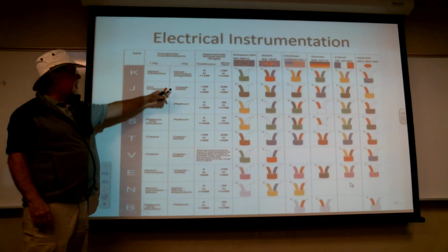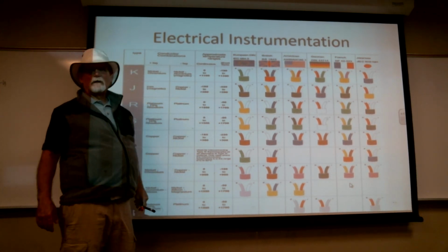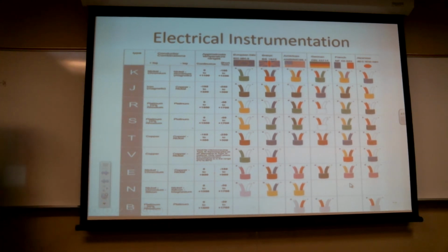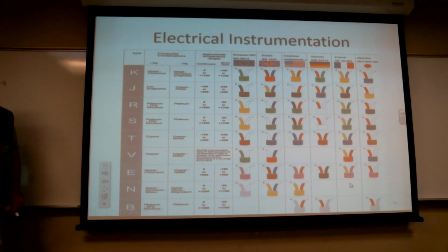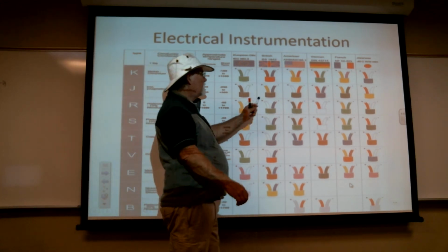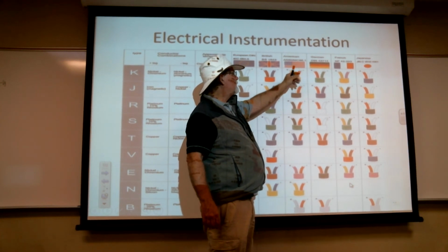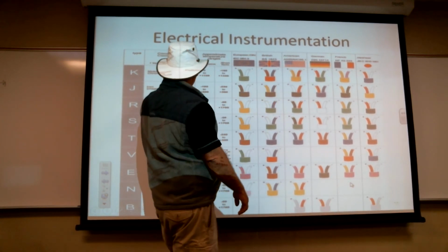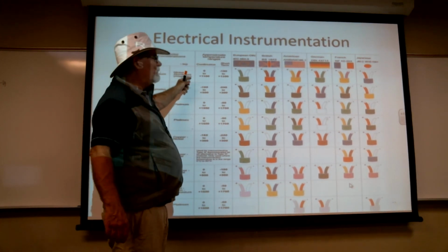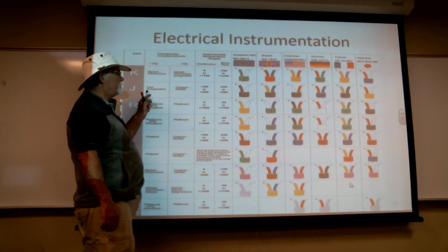J-type is going to be iron and copper nickel. Again, a much narrower range and lower range operating temperature. And then there's a whole bunch of different ones. What you're going to see most commonly, yellow and red, sometimes with a yellow insulator on it, is always going to be your K-type for your EGTs, and then white and red are going to be your J-type for your CHTs.